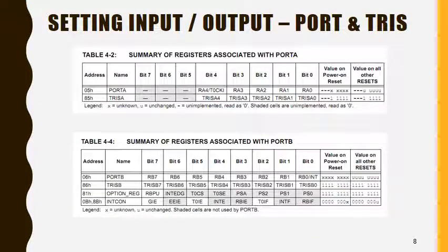If we refer to the datasheet, in the PIC16F84A datasheet, the registers associated with port A are the PORTA register and the TRISA register. Here we have the address information as well. When we write the word PORTA in our program, what the microcontroller understands is that it needs to communicate with the location at address 05.